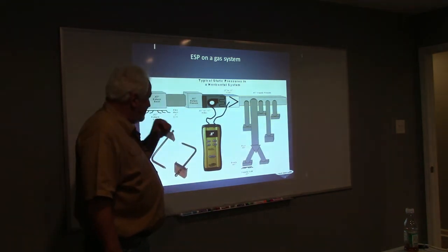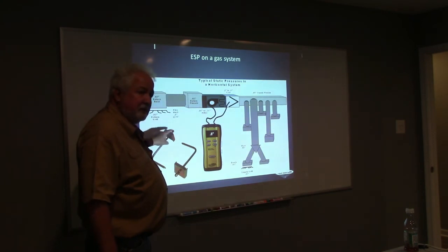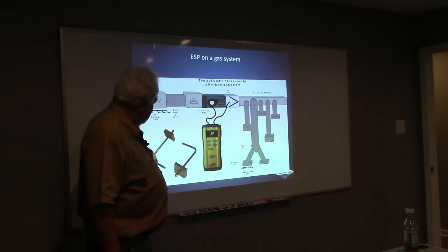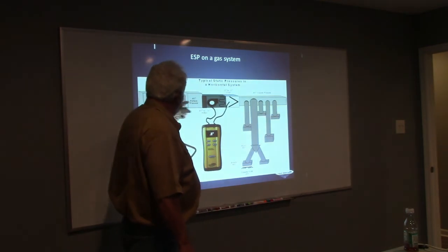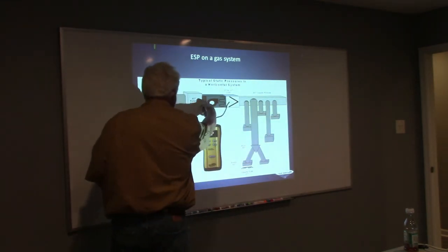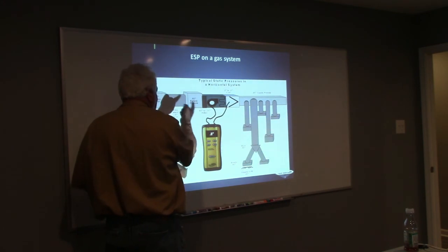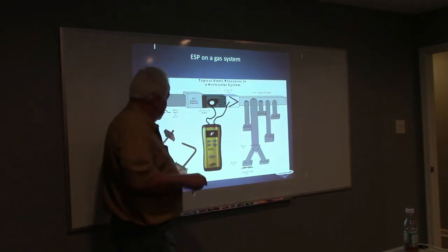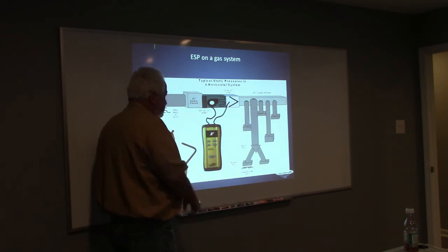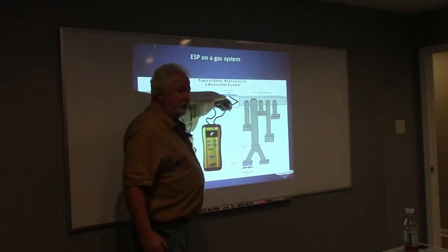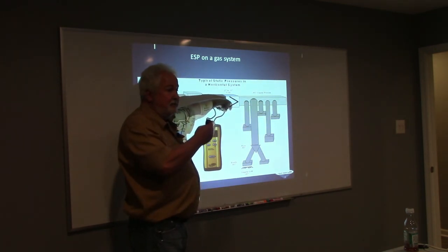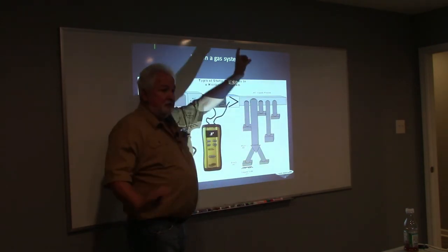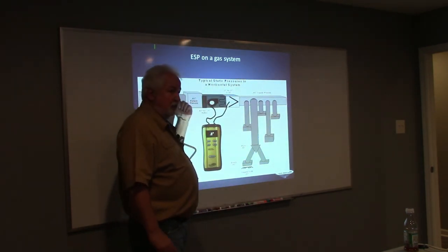0.8. Well, is that good or bad? I like these fittings, and I don't know if you had these on yours. Yeah, you did. Look, either point it in the direction of the airflow or where the airflow came from. So it doesn't really matter which way. You've got the arrow written on yours so you can see which direction it is. Just don't have it at a 90 degree, because now you're getting velocity pressure on that piece. You want it to be static pressure. So point it either in the direction of the air or where the air came from.